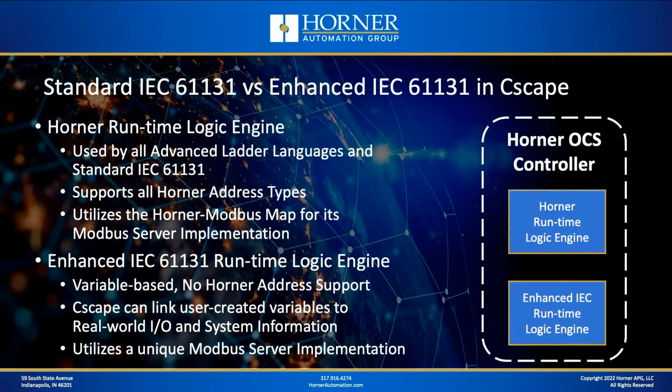runtime logic engine. Again, used by all the languages except for enhanced IEC. Because it utilizes the traditional logic engine, it fully supports all Horner address types. So the I's, the M's, the T's, the R's, those are all supported by the Horner runtime logic engine. And because of that, it can very easily use the traditional mapping method for Modbus server. So because T's and M's and R's exist and they can be mapped to variables, it's very simple to go ahead and map those over to Modbus addresses.